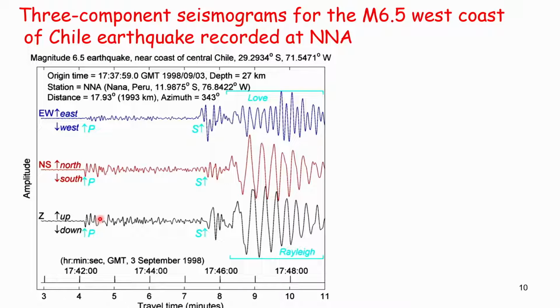These are very important aspects to understand how the mediums act and where you are located compared to the earthquake. This is again a typical magnitude 6.5 earthquake near the coast of central Chile, recorded at a particular location, where you can see that the amplitudes of the S and P waves are considerably lower than the surface wave amplitude. So, sometimes you will get a dominant surface wave at a particular location, depending upon the earthquake origin and where your station or building is located.